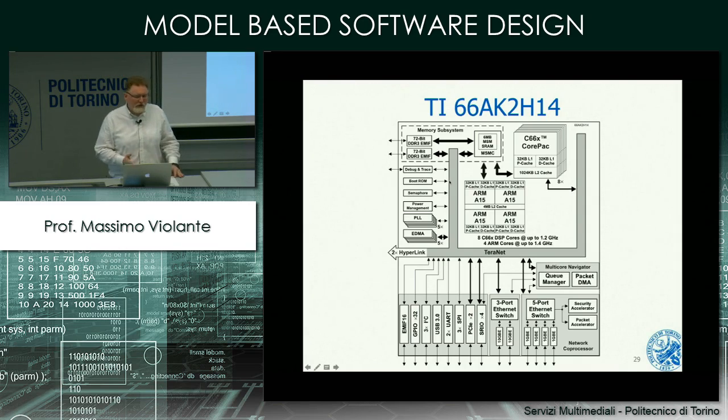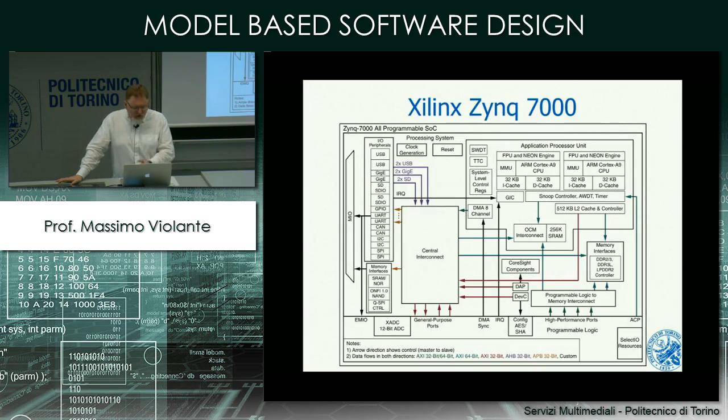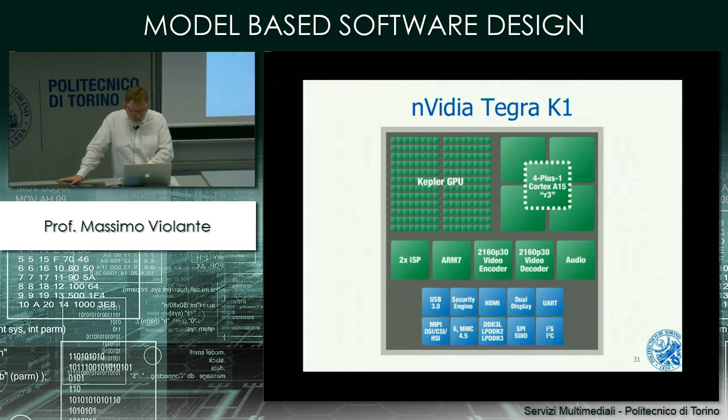So you can clearly imagine that this is not going to be a cheap device, and this is not something that you have to deploy for very trivial tasks. So if you have very computing-intensive applications, then you want to have such a kind of beast. Otherwise, it is an overkill. This is an example of a Zynq device. You may have heard about this. This is an example of a single chip that hosts processor plus FPGA.